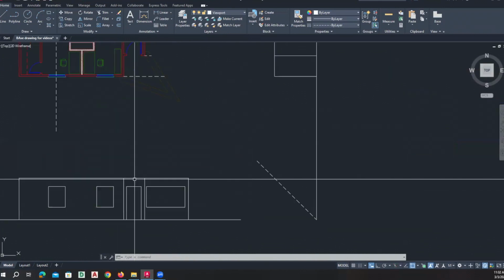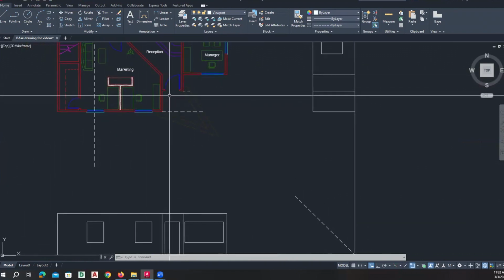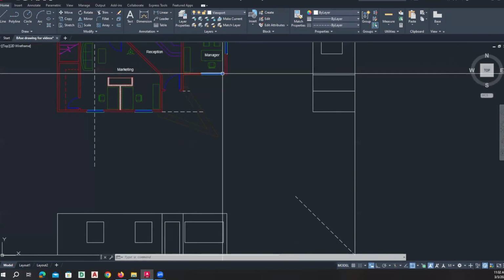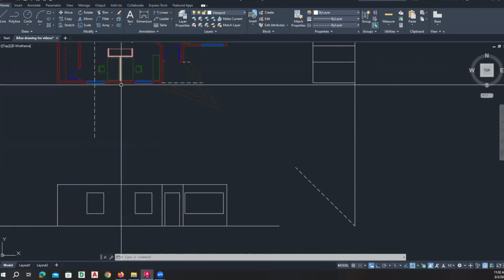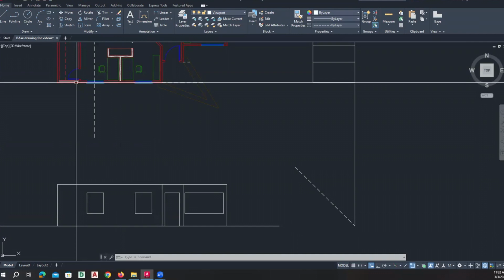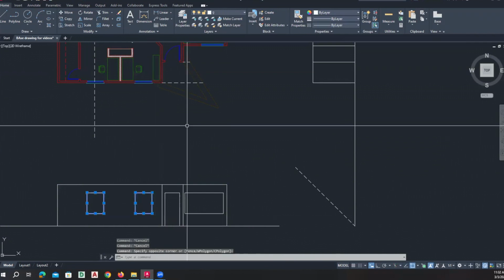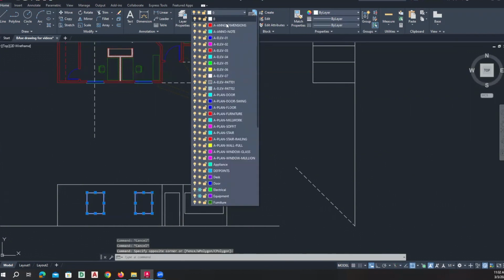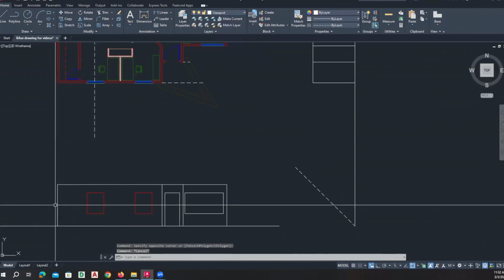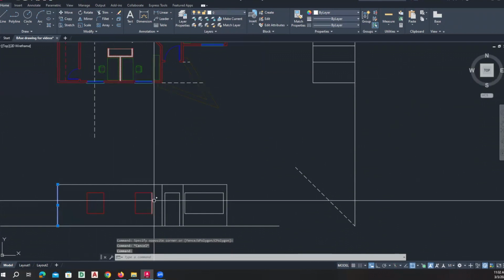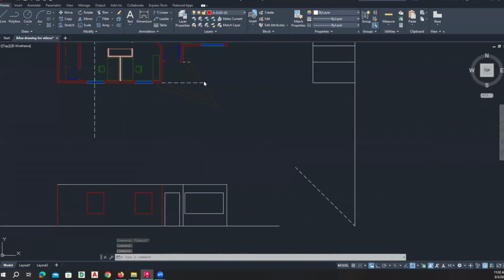So if I take one of these elevations that I've already drawn, although very simple, we can look at some of the line weights, right? Let's say this portion of the building is the closest, this is the second closest, and this is the furthest away. So what I would do is break up this drawing so that the portions which are closest will be the darkest. Like these windows, I can put those on a layer like ELEV, let's say 3, right? This is also the same distance from me, and I will put that on the same layer, ELEV3.